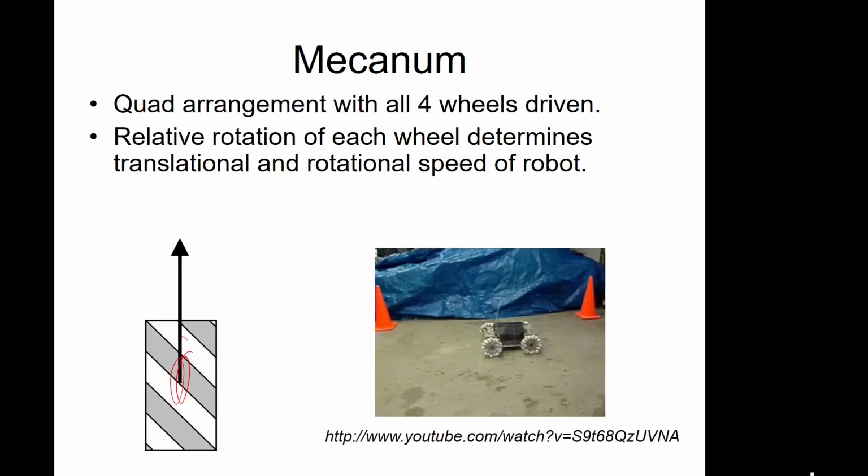And the wheel gets driven forward, but because you've got rollers on the side, you don't actually get a pure force going forward. What you can do is resolve that force into two components, which are perpendicular to the rollers and parallel to them. Now you're not going to get any motion parallel to the roller. It's only allowed to roll in this direction. So the roller will only roll in this direction, so you won't get any motion due to that component. You'll only get motion due to this component.